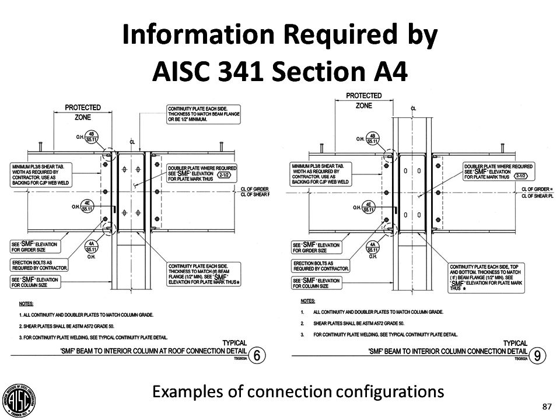be configured. Plate sizes and things like that that relate to specific requirements, those might be shown on your frame elevations, for example, such as the thickness of the doubler plate. But if a doubler plate is required, this is where that information might be shown.